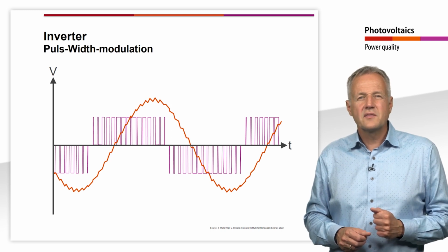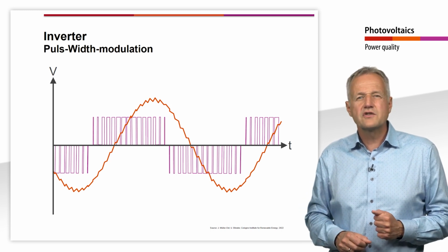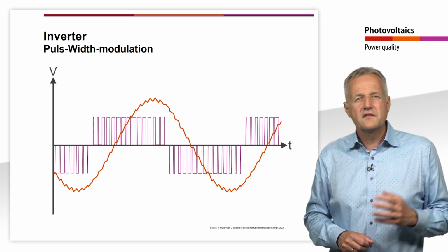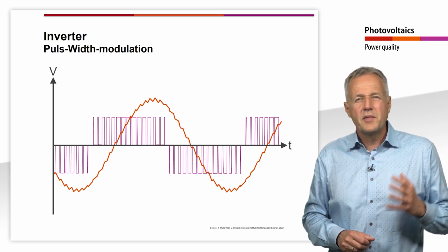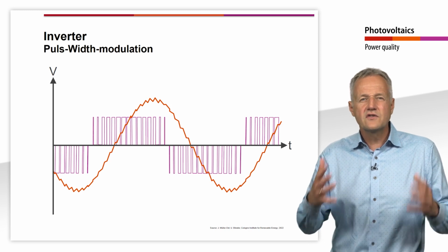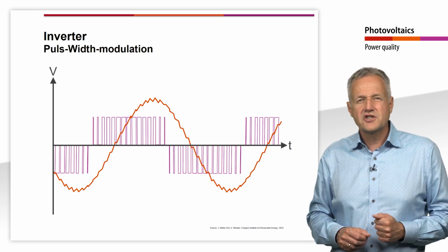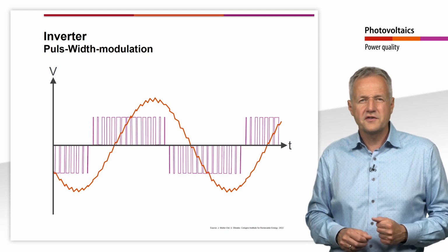In larger systems, it is therefore recommended to monitor the harmonics. If the overall harmonic level exceeds the acceptable limit, it may be necessary to use attenuation measures such as an active or passive filter.